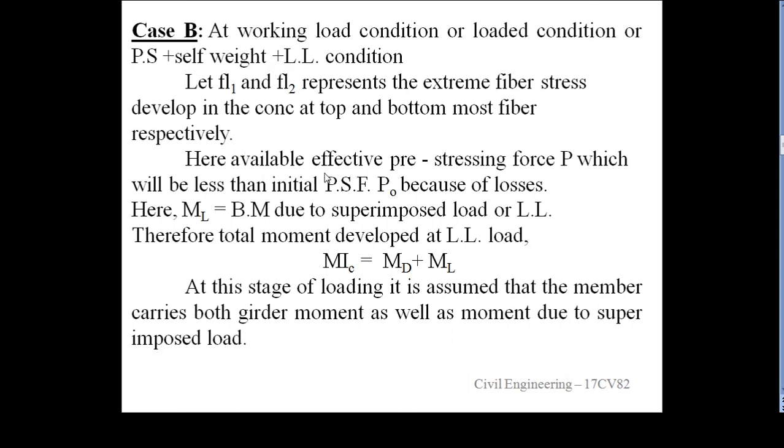Here the available effective pre-stressing force P will be less than the initial pre-stressing force P naught because of losses. ML is the bending moment due to superimposed load or live load. Therefore, the total moment at live load condition is MT equal to MD plus ML.